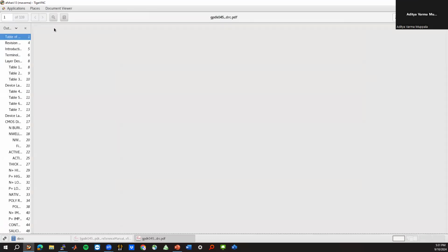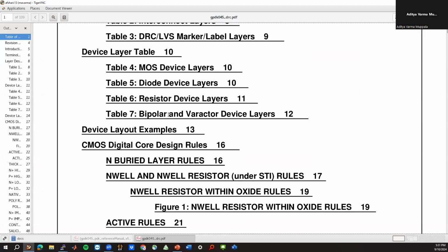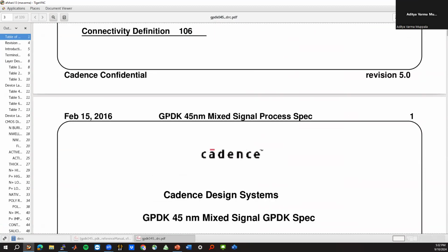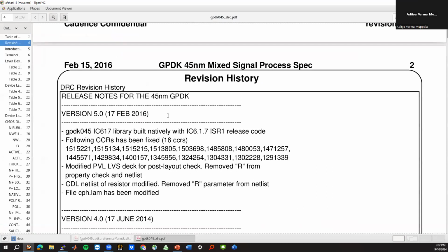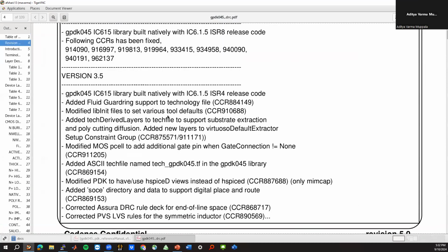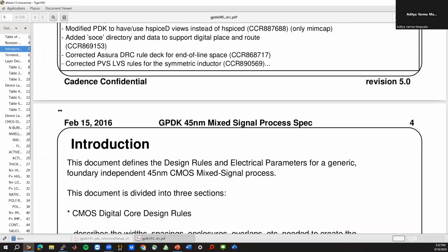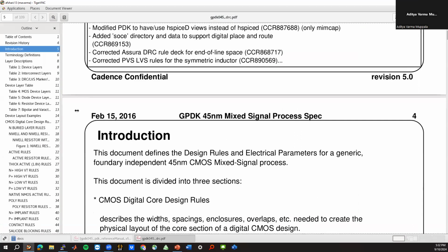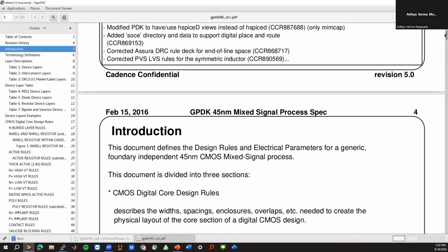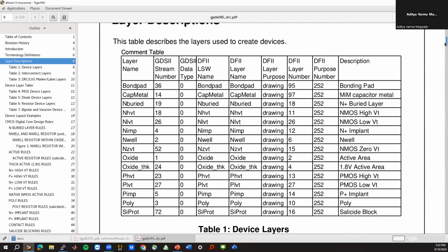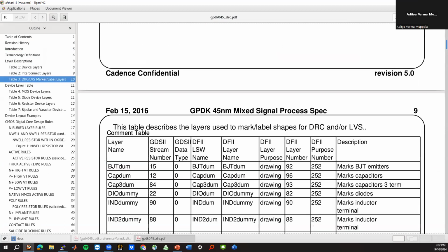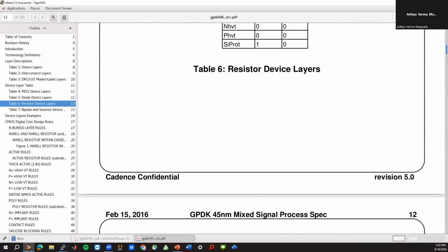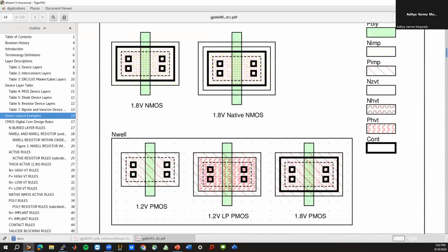But anyway, I just want to mention that you can also go through these documents. They have a lot of information. It's very important to actually read the entire PDK from start to end, in case you miss something. So for example, some processes have like a 90% shrinkage in the sizing, and you need to account for that when you design passives and things like that, right? And for example, in this PDK, it gives you all the metal layers and all this information that we will be using in the future.